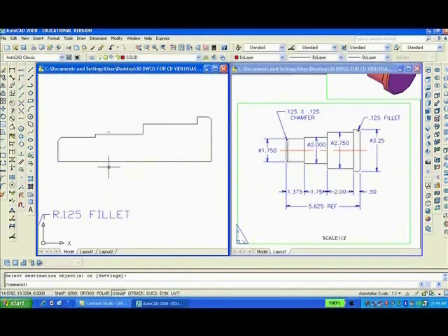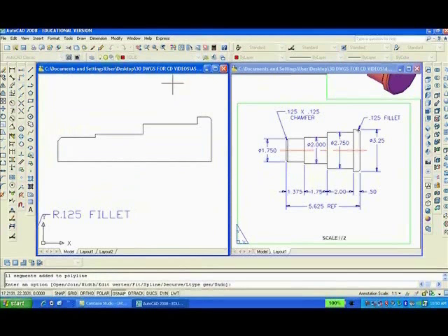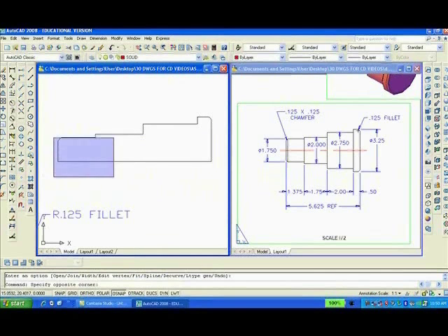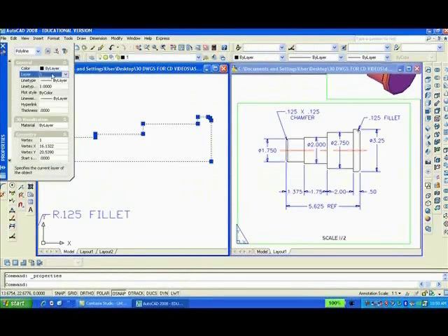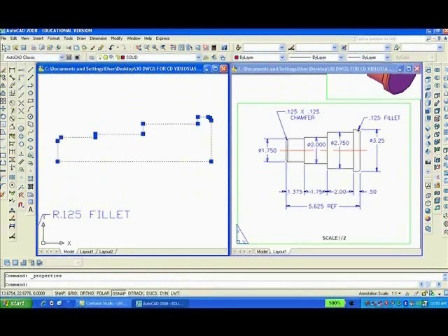We're going to use a different technique. We can't extrude the shaft. We're going to have to revolve it. But first off, what I'll do now is type PE enter, polyline edit, make it a polyline, yes, J to join, make a window and put them all together, make one line out of it. Then what I want to do is to select it, enter, select the object and change its layer, put it on layer solid, should turn red hopefully.